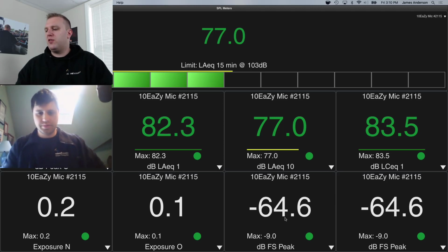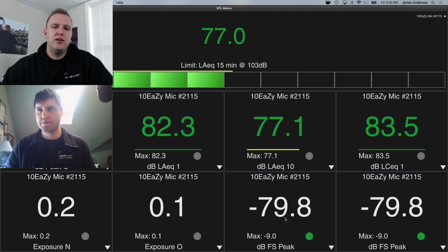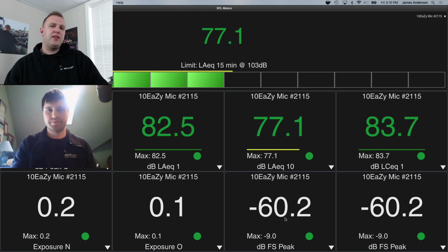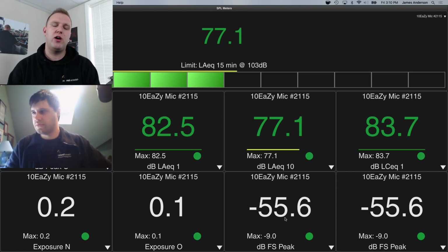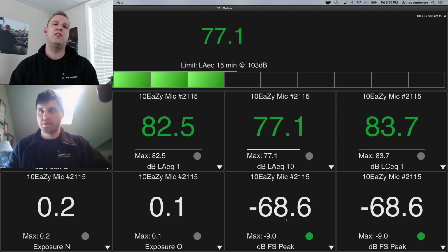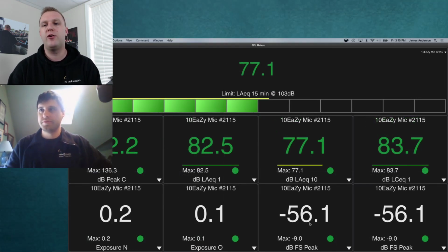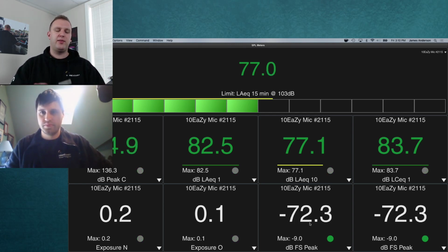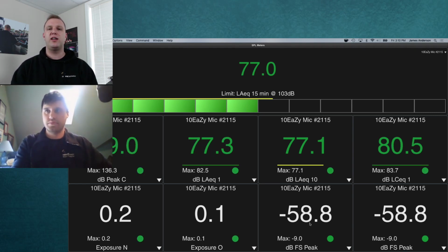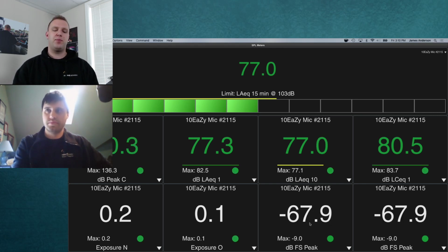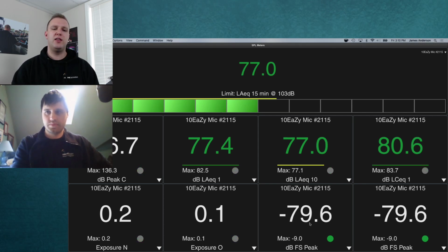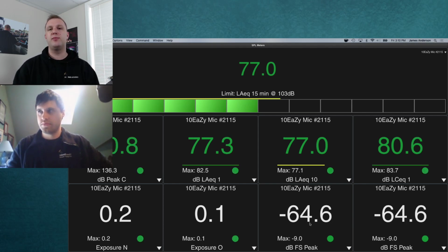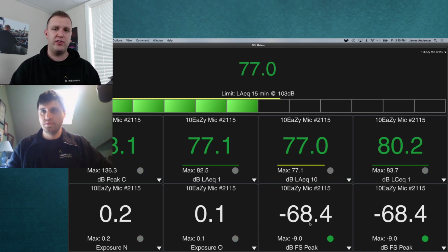Yeah, just one more thing. It's how simple do you need it? Is the person that's operating the SPL measurement system a qualified sound engineer that will understand how to calibrate a microphone and follow a procedure to do that accurately? Because for simplicity, a 10EZ system is just you connect the USB cable and launch Smaart, and you're calibrated for SPL and start logging. So there's certainly something to be said about both the accuracy as well as the simplicity that a turnkey system offers.